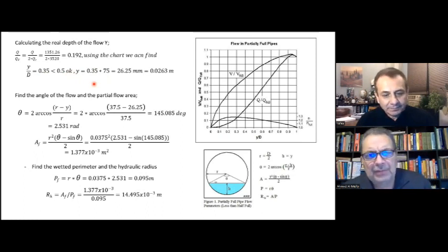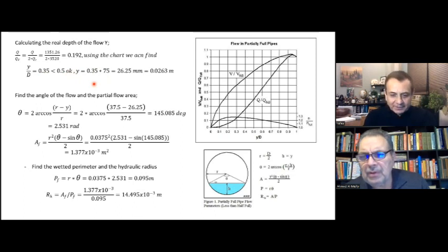One question I have here for Q full or Q: where are you laying the pipe exactly? How do you assume that the whole seepage flow from the embankment is going to that pipe? Because we are assuming two-dimensional flow. All of these are two-dimensional flow. I understand, but are you really assuming that all the flow will go to that pipe?